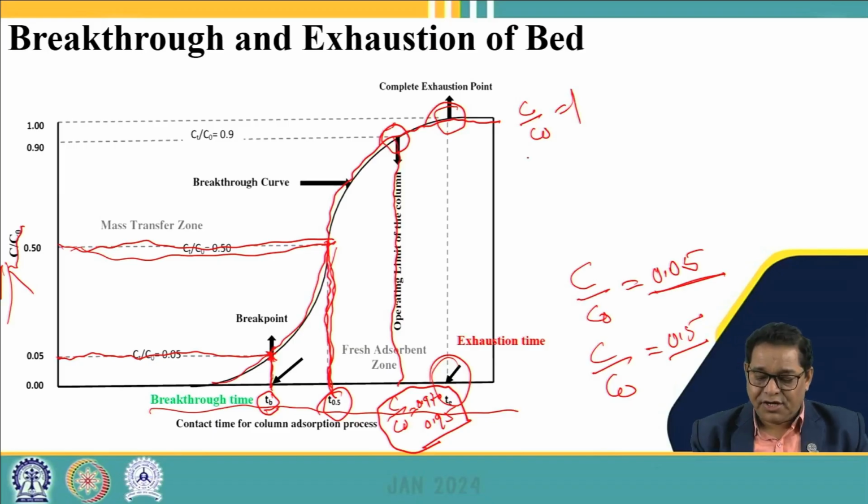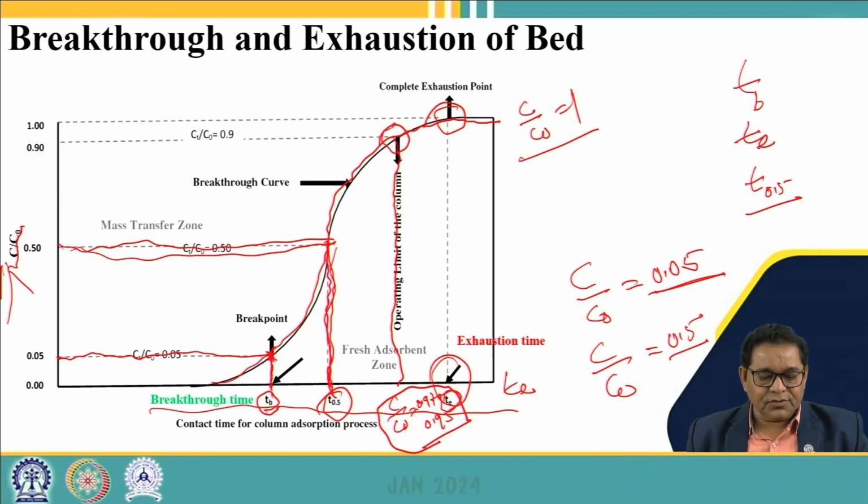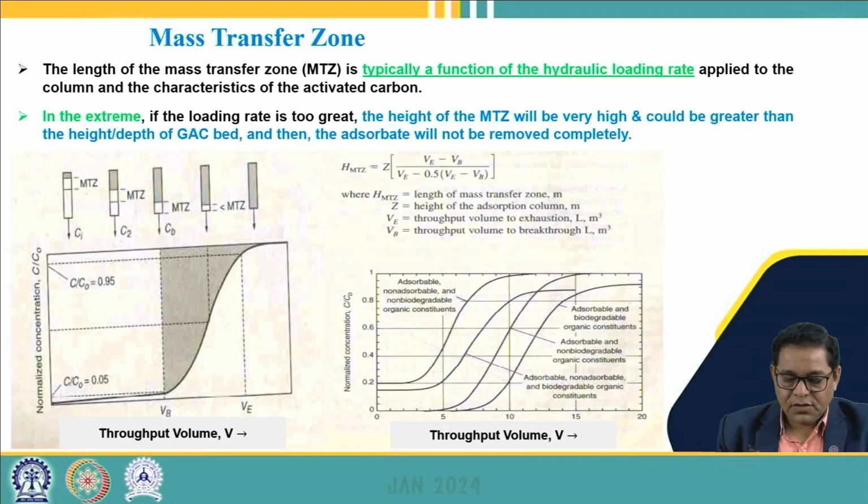Then this point is called the complete exhaustion of the bed, and this is defined as the time of complete exhaustion, that is TE. So here this breakthrough study is carried out not only to find out the breakthrough time, but it is also carried out to analyze the type of adsorbate, its nature, what type of adsorption is occurring.